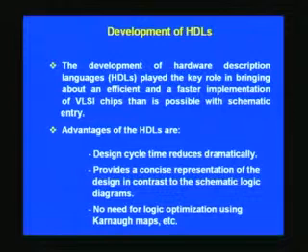HDLs. HDL has brought about, so to say, a revolution in digital design, in the sense that the cycle time reduces very dramatically, and from my experience I can say there is 3 to 5 times speeding up of cycle time. It provides a very concise presentation in contrast to the schematic logic diagrams. There are what are called behavioral statements and RTL statements, and all this can lead to a very concise description of the digital hardware that you are designing.